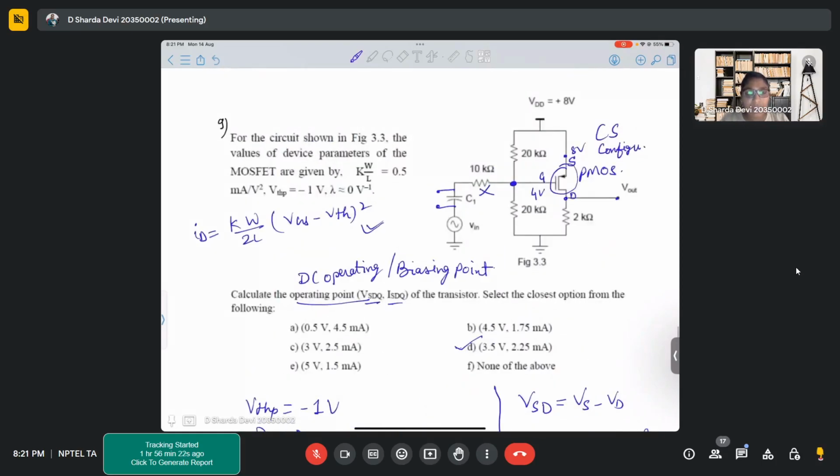Ma'am, I have a doubt. When we calculate VG, the operating point, we consider the voltage applied across VDD, that is the DC point, right? Yes. So when we write a small signal circuit for it, the VDD we are going to make it 0. So VG, which is a function of VDD, will also be 0, right? Why? At that time, you will have your V in. But VG is due to only VDD, right? No, that's how we calculate VG by the voltage divider method.